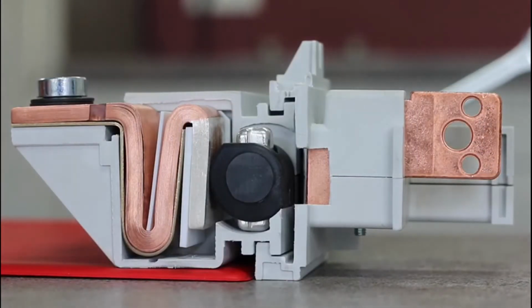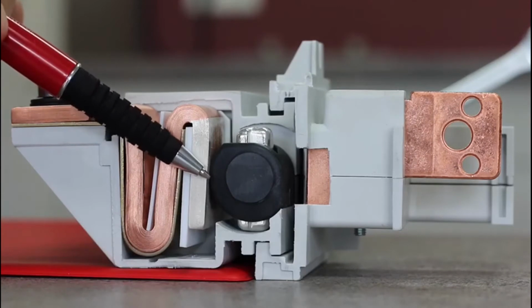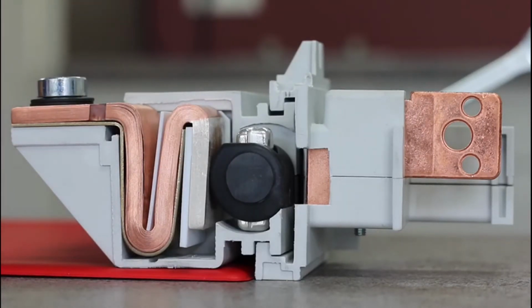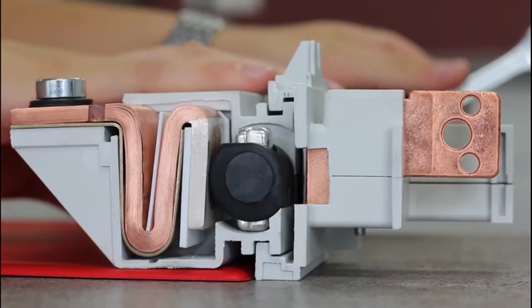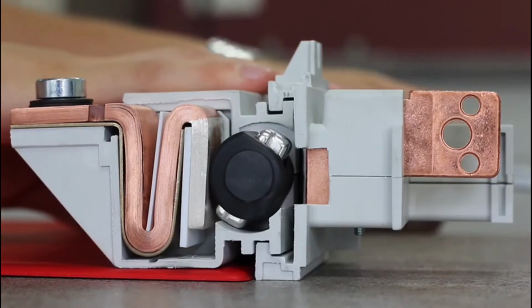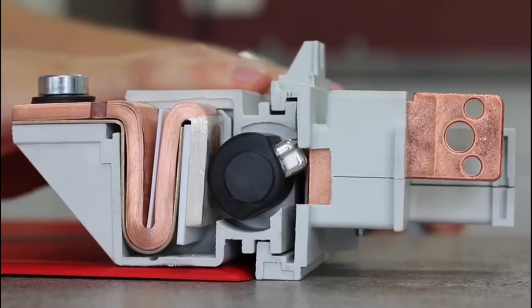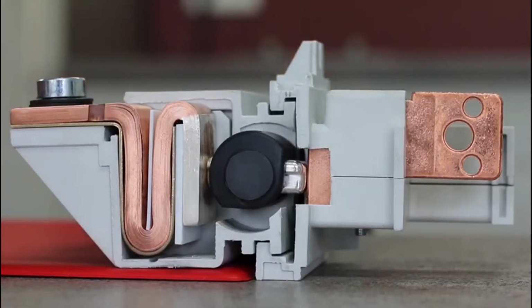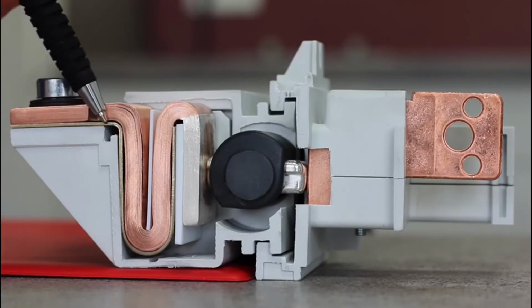The video shows the connecting and disconnecting of the pressure contact. The braking is done on both sides. It's a rotary-based double braking. The contacting bolt slides with a hard pressure over the contacting areas at opposite side and works self-cleaning. The strong flat spring together with the high flexible copper layer take care about an optimal pressure force at any time.